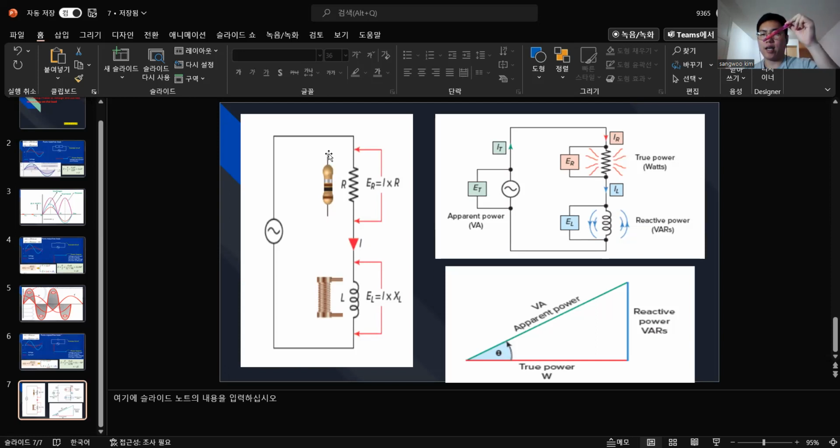Like this angle, right? Between voltage and current, this is voltage, this is current. So between this angle, if we do cosine, it's the power factor. And the impedance angle is also the same, right? There's true power and reactive power. We learned about that, right? Yeah, that's our today's lecture, guys.